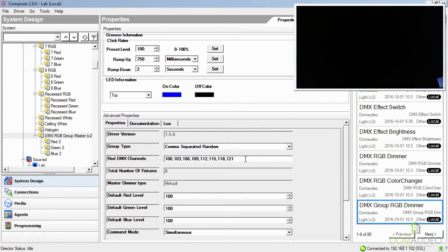Random channel is useful when there is a bunch of lights to control, but they are not configured with subsequent channel values, or if there is a DMX device that uses a channel value in between the first and last channel of the light group. This is to prevent sending commands to that device when controlling the group of lights.